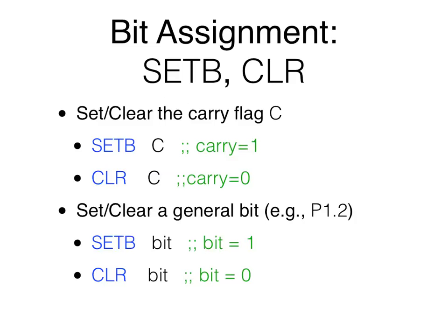That's PSW.7. So one letter difference, they do exactly the same thing, but the top one uses a single byte. The bottom one uses 2 bytes, because the top one does not name the C explicitly. The bottom one names the CY, namely the bit address of the carry flag, explicitly. That's why it needs 2 bytes. Just like the A versus ACC. A is implicit, ACC is explicit.